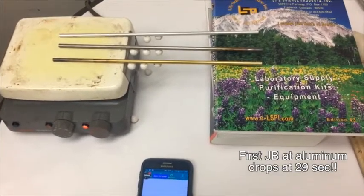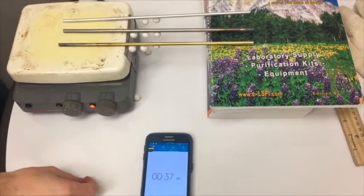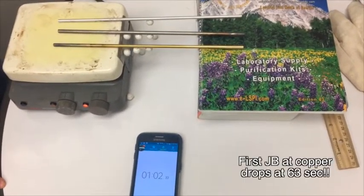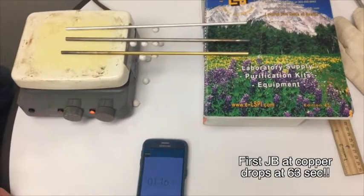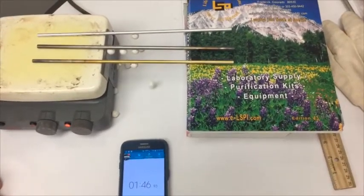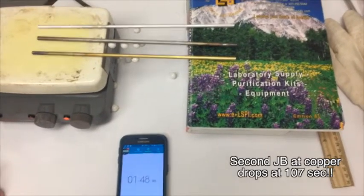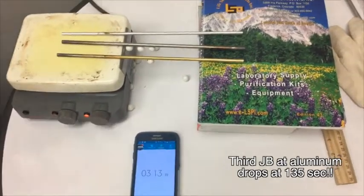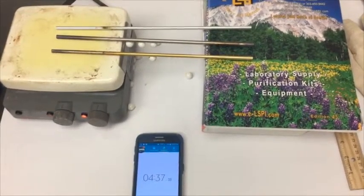As predicted, the first jawbreaker on the aluminum rod fell first, followed by the second one on the aluminum rod and the first one on the copper rod. Because the difference in thermal diffusivity was so high between aluminum and steel, all 3 jawbreakers on the aluminum rod fell before the first one did on the stainless steel rod.